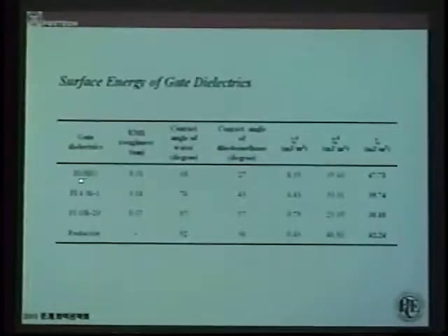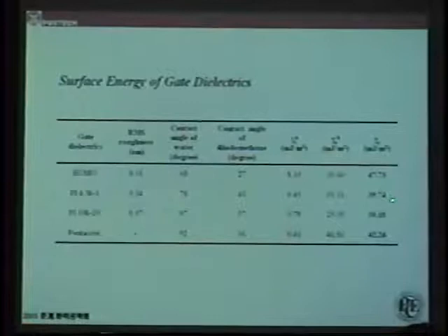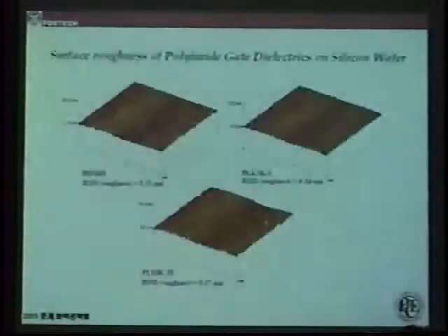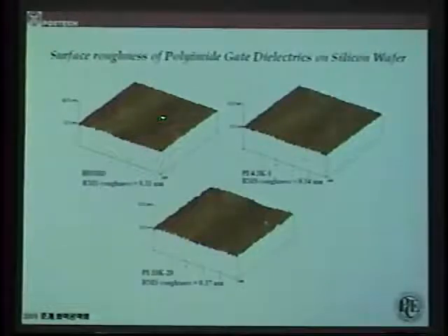So, in this way, we measure the surface energy through contact angle measurement. Homopolymer is like 50 and 40, and if you add 10,000 molecular weight PDMS, 30. Compared with pentacene, which is about 40, the homopolyimide has a higher surface energy than pentacene. In the case of the silicon modified one, it is less than pentacene. And this is the roughness, showing almost the same roughness. This is again showing the roughness of the polyimide surface by AFM, about 3 angstrom.